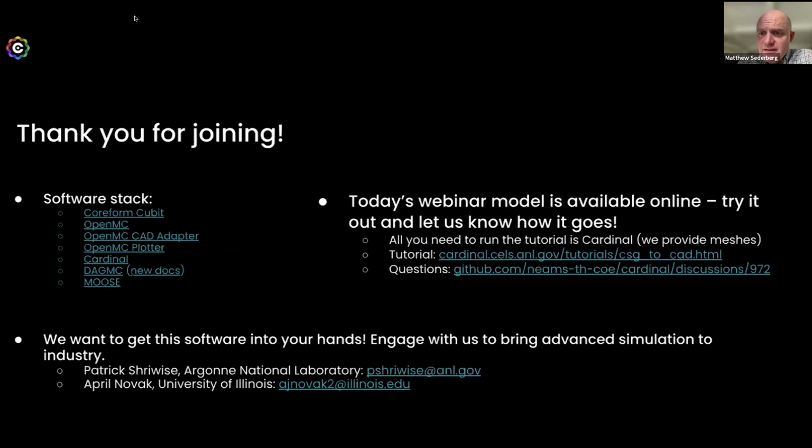So this is a question from Kent, going back to Patrick's part of the demo. If the surface mesh and volume mesh have the same conformal mesh, I guess that means that only tetrahedral meshes are supported for volume tallies. And are there any limitations from that?